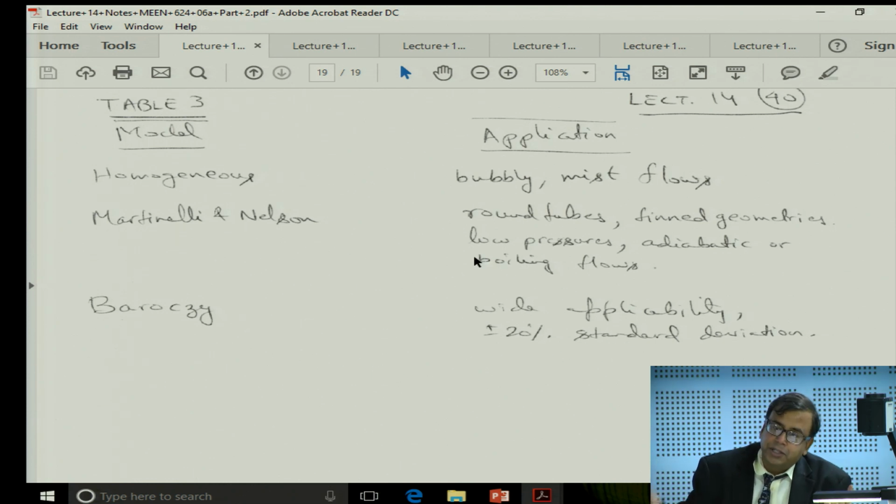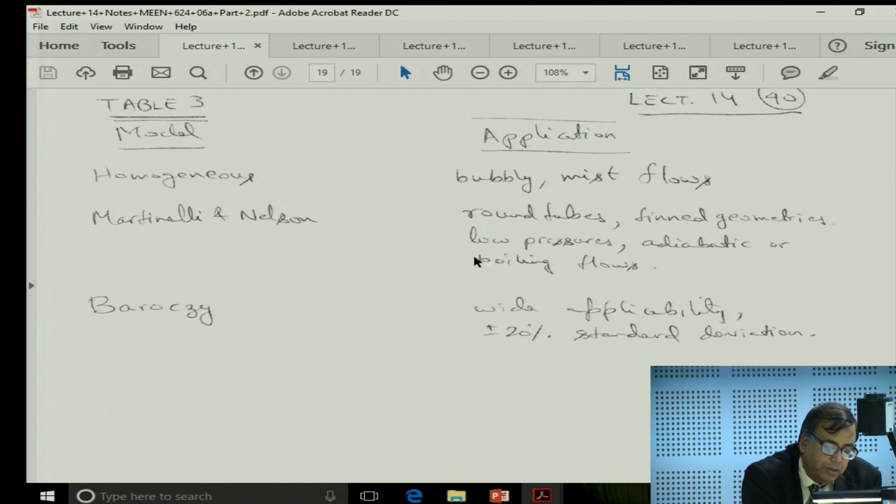That is the next question I want to answer, which means at each and every segment of that pipe I need to calculate the heat transfer coefficient. There are a lot of heat transfer correlations out there. In the interest of time, I will just highlight one. The one I like the most is known as the Chen's correlation, and there are a bunch of other ones, they are there in your handout, you can look into it.